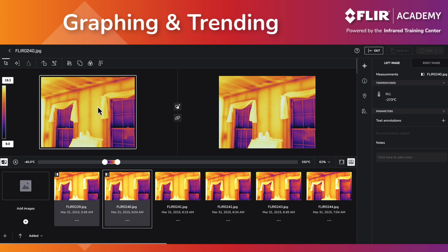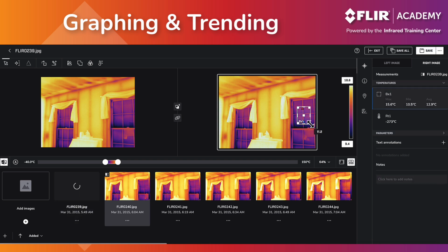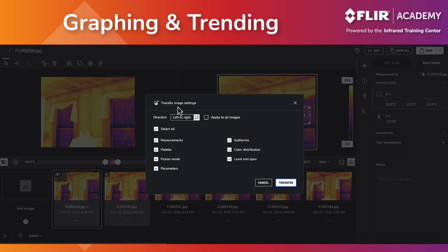For the purposes of this demonstration, we're going to look at the window to see how the temperature changes over time. To do that, let's put an area box over the window in the first image. Click on Transfer Image Settings. And since the first image in the sequence happens to be on the right, let's switch the direction to apply the settings and make it right to left.